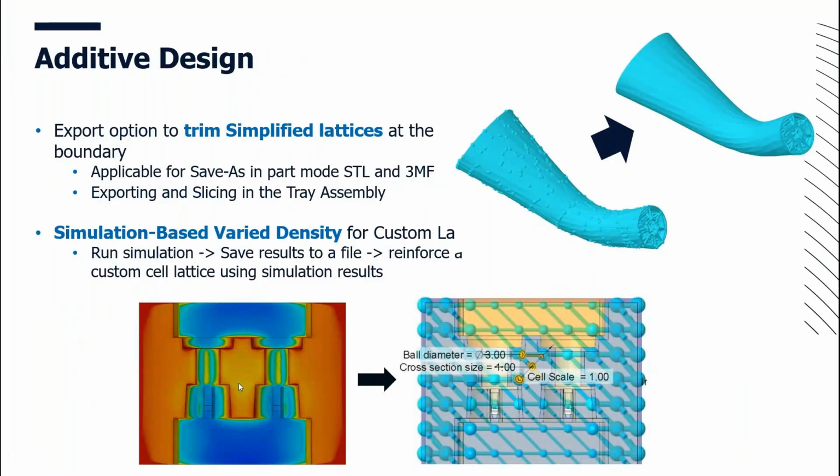Additive design. So again, our printing. When we create some lattices, it's again the same question. Yes, a lot of plastic printing programs can add those lattices themselves, but we don't have control there over the strength of our part. And that's what we want. For metal, for complex parts, we want that strength to be tested before we start printing, because the material that we print in is very expensive, right? So that's why we make those lattice structures in Creo.